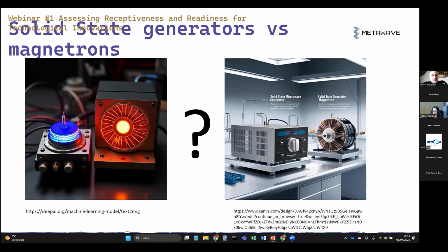But basically, you're all familiar with magnetrons because if you own a microwave kitchen oven, it's operated by magnetrons. And probably you have noticed during its functioning that it operates based on a duty cycle. So it's an on-off procedure of emitting microwaves. When it comes to industrial scale generators, of course, we can no longer use this quite simple approach, and usually we have more complex power supplies, like switching power supplies, which allow for the continuous variation of the power emitted by the magnetron.